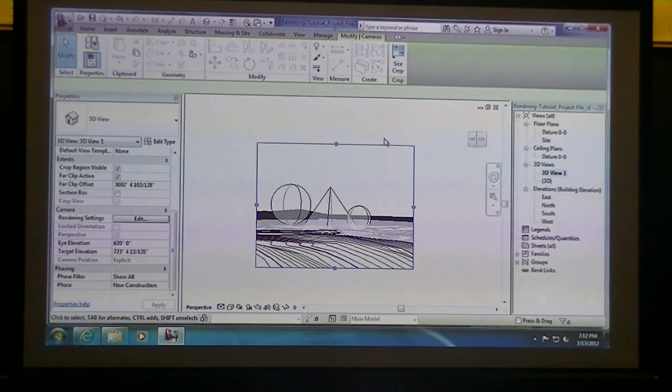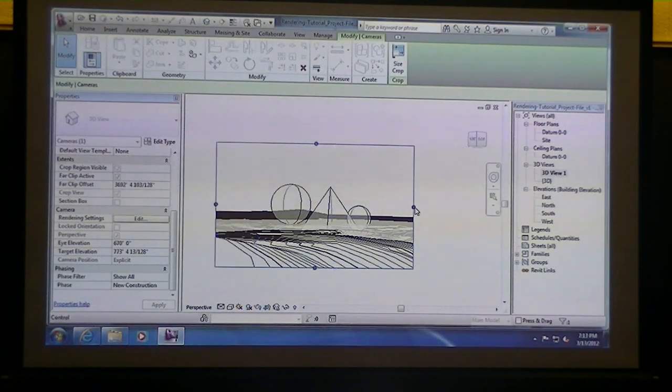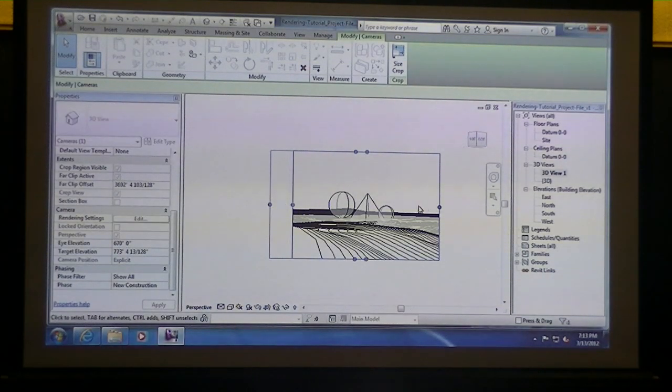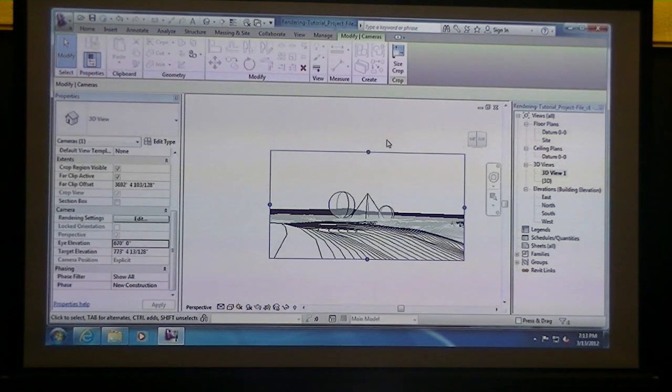We can also click on this view and change our boundaries, our clip boundaries. So we can begin to manipulate how much more of the view in the scene that we can see. By default, the camera is giving you that 30 cone of vision, your 30 degrees on either side of your eyeball.